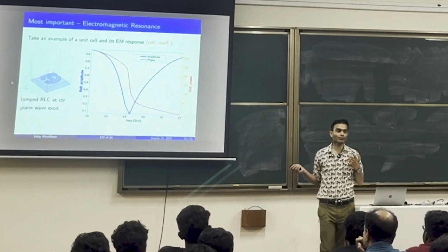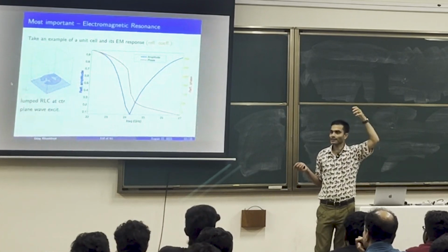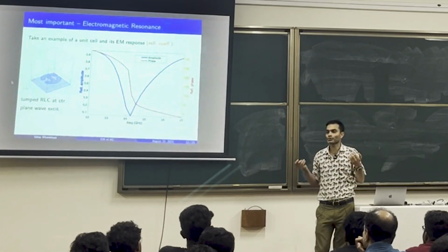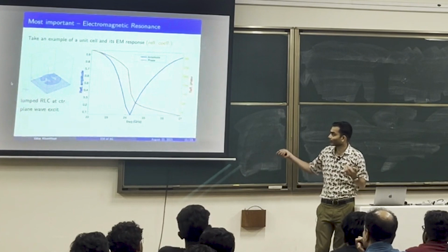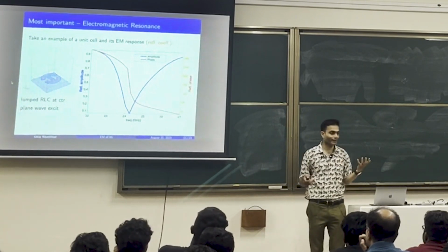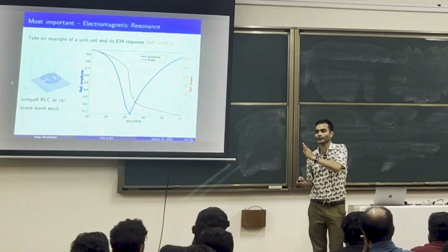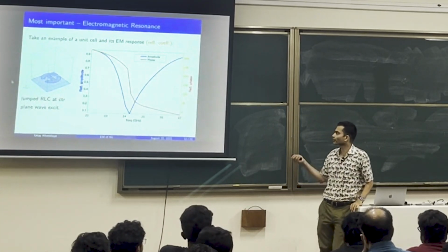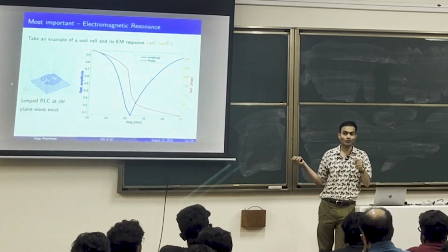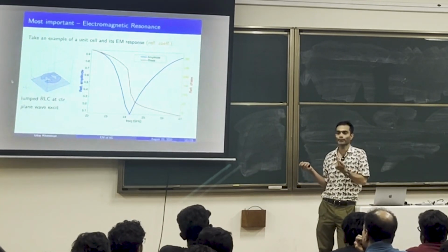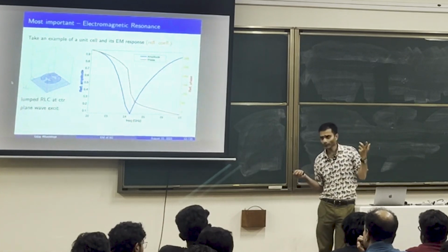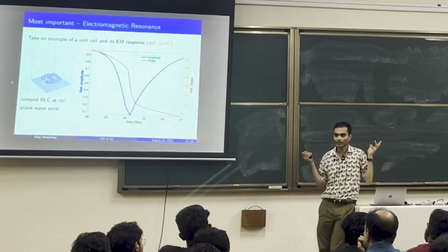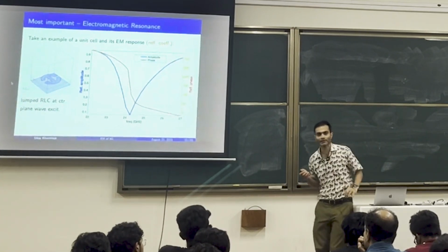And again, this is not something very exotic. Water has resonances in the optical frequency range, which is why you are able to see a rainbow, right? If I talk about this in terms of refractive index, different colors see different refractive indices, which is why a rainbow splits light or bends light, right? That same concept now we are using at gigahertz frequency. So the presence of a resonance is extremely important. If there were no molecular resonance in water at optical frequencies, you would never see a rainbow. It's as simple as that. Okay, so this resonance is a very key point.